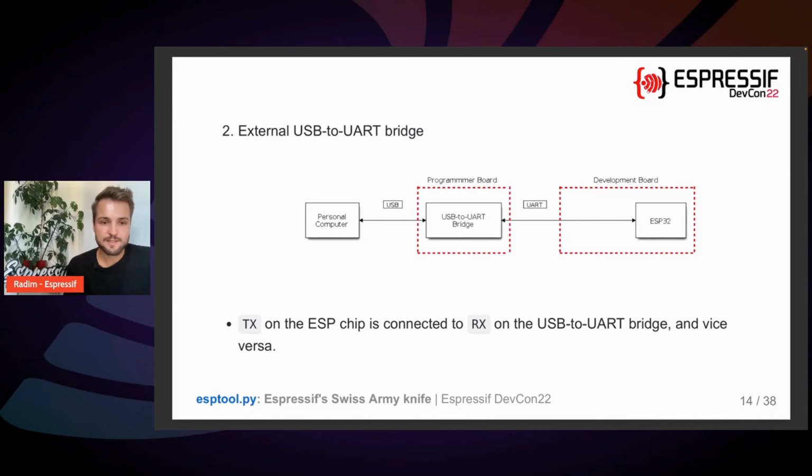There can be cases where you don't have a dev kit or you're connected to a real device, such as this one. Here I have an ESP module, which doesn't have the USB to UART bridge.